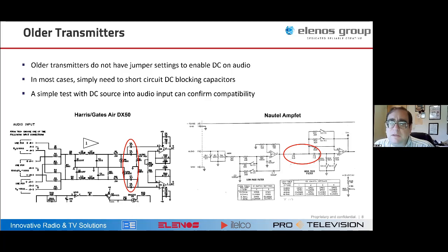Well, you mentioned that it's going through. How low a level is the noise? There's got to be something for AM transmitters. 70 dB is the number for signal noise that we always try to meet for AM. Okay. And that's kind of what we're trying to shoot for.